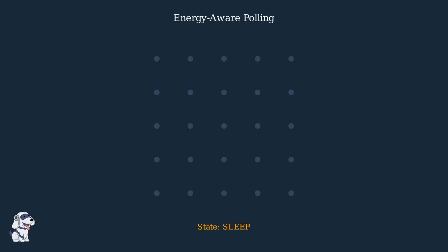In standby mode, the sensor grid enters a low-power sleep state, periodically emitting a faint, low-frequency pulse to monitor for proximity. As soon as the hardware detects a nearby object, it signals a wake-up event, immediately shifting into high-frequency active mode. The system now initiates a 1,000 Hz scan across the grid, ensuring lightning-fast touch detection only when it is actually needed. This smart resource allocation preserves battery while maintaining the instant responsiveness that modern users expect.